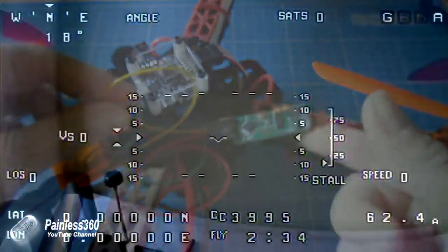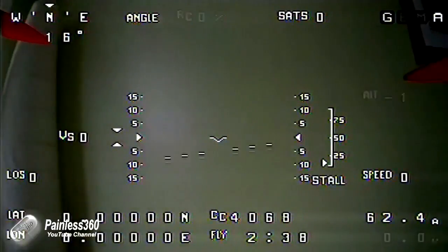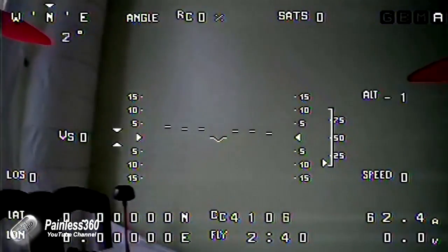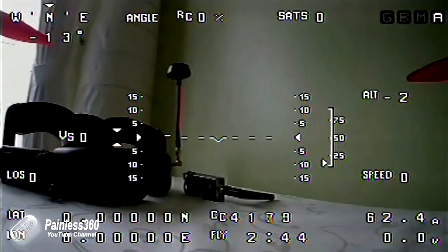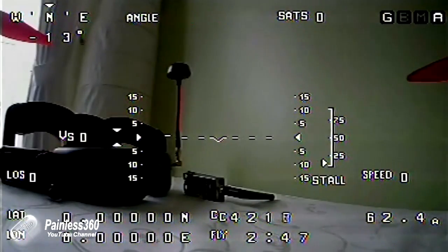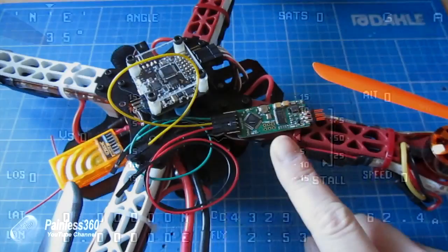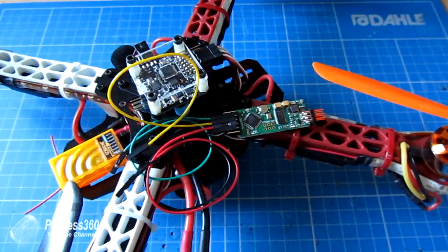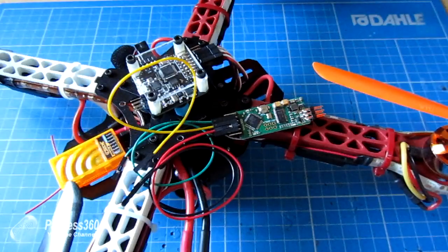Now I've added these boards to other flight controllers in other video series, and you can actually see here one that we did for the multiwii. And as the Naze32 shares an awful lot of technology and code with the multiwii, we can do the same on here, but it's a little bit more interesting. A couple of reasons. One is we don't have all the same ports, so we have to have the pins going to different places, and there's an extra bit of soldering that we have to do too.